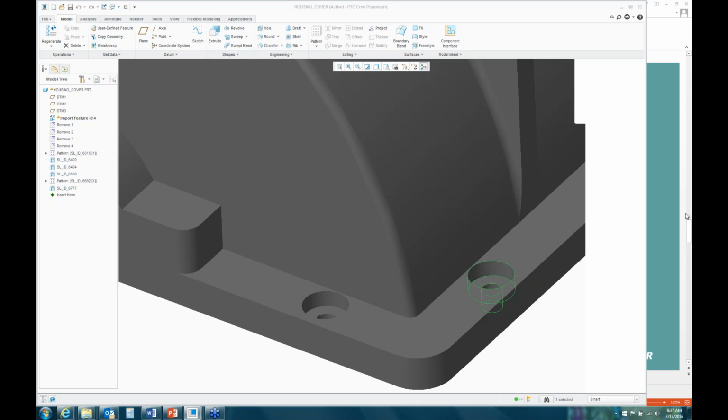Okay? That being said, you can have a search path with all those fasteners, and then you wouldn't have to keep them in your working directory as long as you could find them in the search path. So you would have to create a search path to point to these libraries, which can be found in the install directories on your system. Or maybe if you had a separate library on a server, you could do that as well.